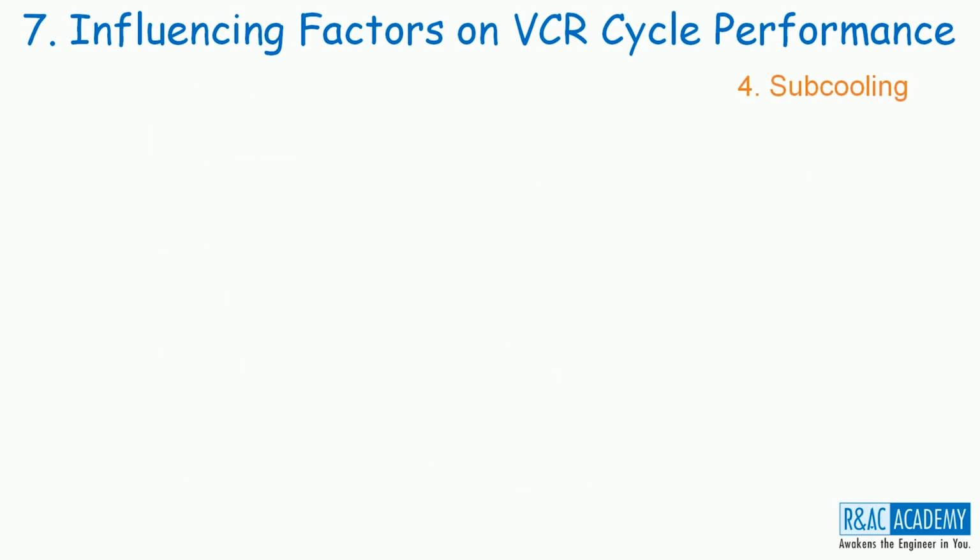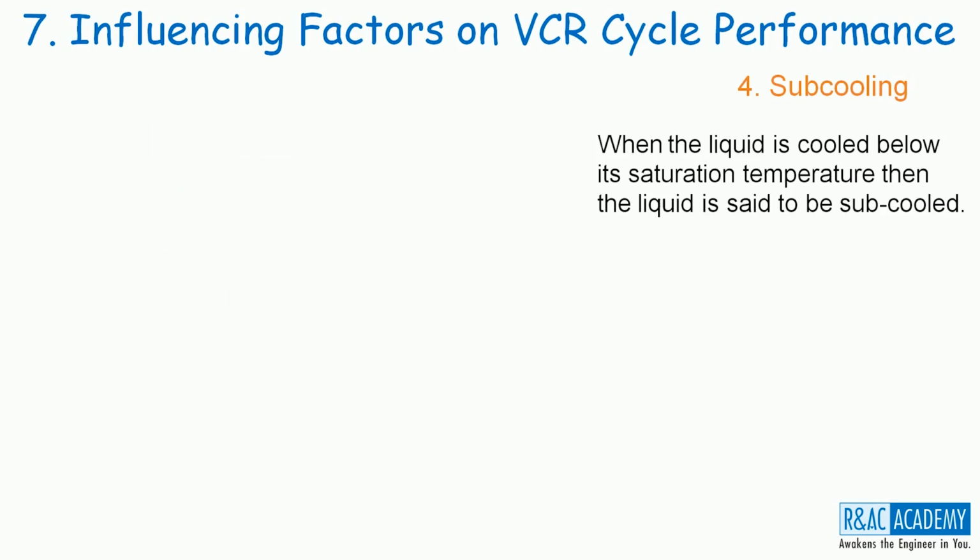The next factor is subcooling. What is subcooling? When the liquid is cooled below its saturation temperature, then the liquid is said to be subcooled. To understand the phenomenon of subcooling, first we should know where the refrigerant exists in saturated liquid state.